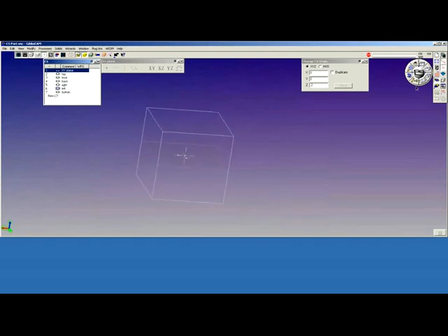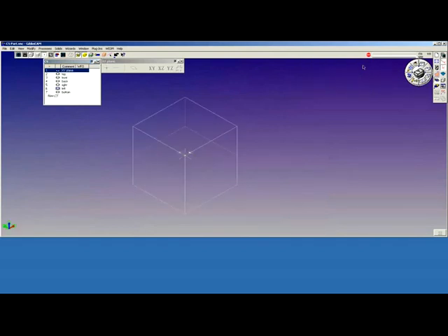All right. So we're back to our original condition. Now, when drawing on coordinate systems, it's typically best to keep the values local to the coordinate system. In other words, build your geometry at depth 0 of each coordinate system. Just like we do in a 3-axis environment where we draw at Z0, we want to draw at depth 0. We always control the depth of the cut with the actual operation or the cutter.